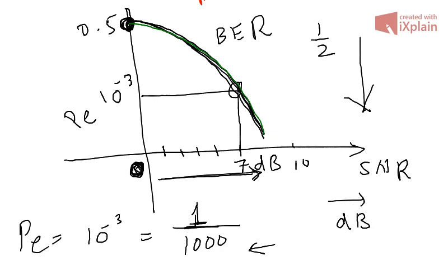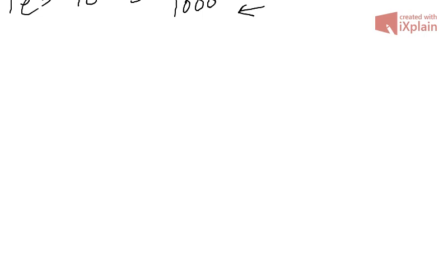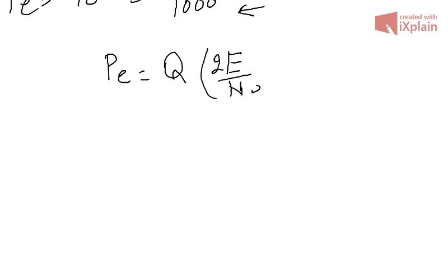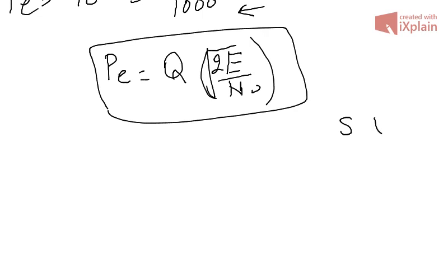The probability of error expression is equal to Q of square root of 2E over N naught, which we get by assuming that s of t is transmitted. Initially we assume that s of t is transmitted, which means that 1 is transmitted and we are getting a 0. So this is the chance that when you transmit a 1 you would get a 0 at the receiver. For different SNR, you can observe those chances or that probability.